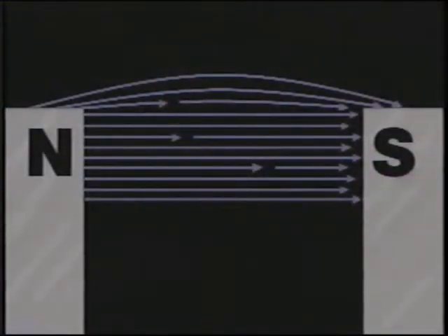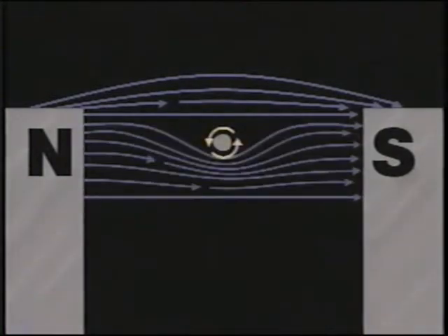You'll remember that magnetic lines of force without any interference will follow the shortest path from the north to the south pole. However, the introduction of circular flux lines from the conductor prevents the magnetic flux lines from pursuing a straight path. This is because flux lines do not intersect. Instead, a complicated relationship develops between the two sets of flux lines.